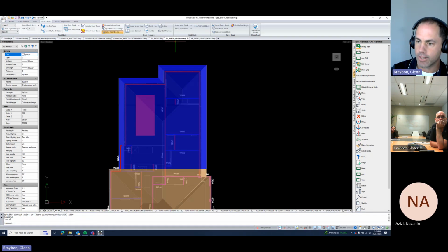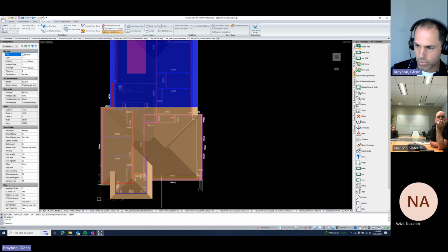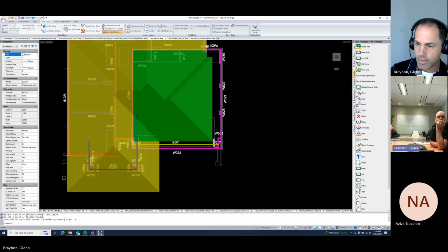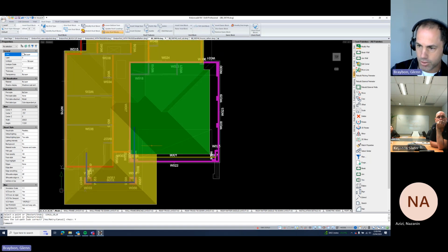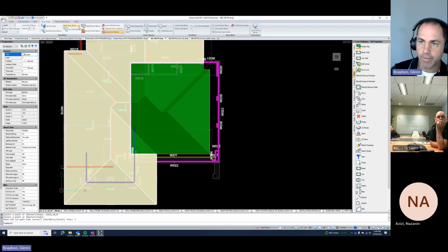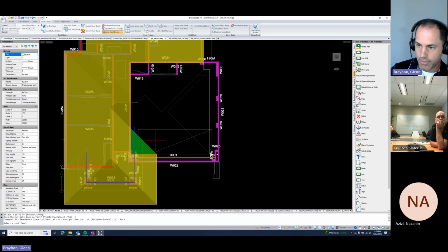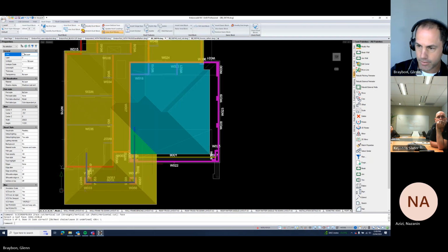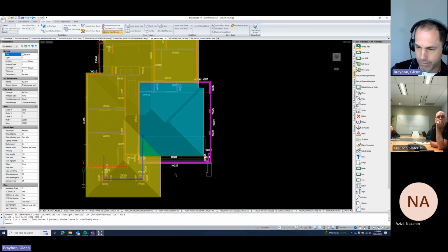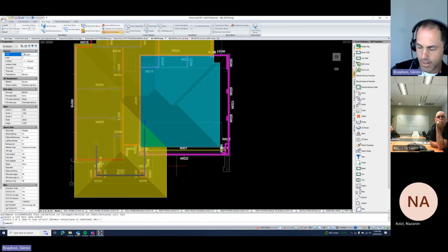I did get it to a point that it worked. I thought that roof cut. Okay, so I'll just do a face cut to get rid of this one. Okay, so I've got a face cut there, and then I'm going to join that one. Join roof blocks. So I've cut that little green face cut off the garage. I'm going to join that to my yellow one.